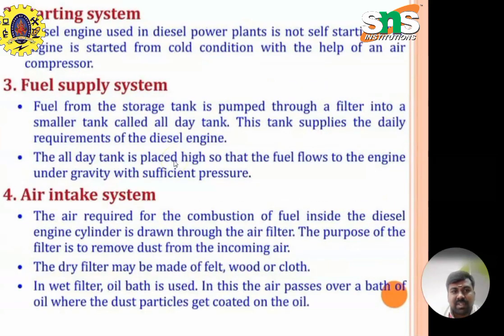Starting system. The diesel engine used in a diesel power plant is not self-starting. The engine is started from the cold condition with the help of an air compressor. The fuel supply system. Fuel from the storage tank is pumped through a filter into a smaller tank called the all-day tank. This tank supplies the daily requirement of the diesel engines. The all-day tank is placed high so that the fuel flows to the engine under gravity with sufficient pressure.